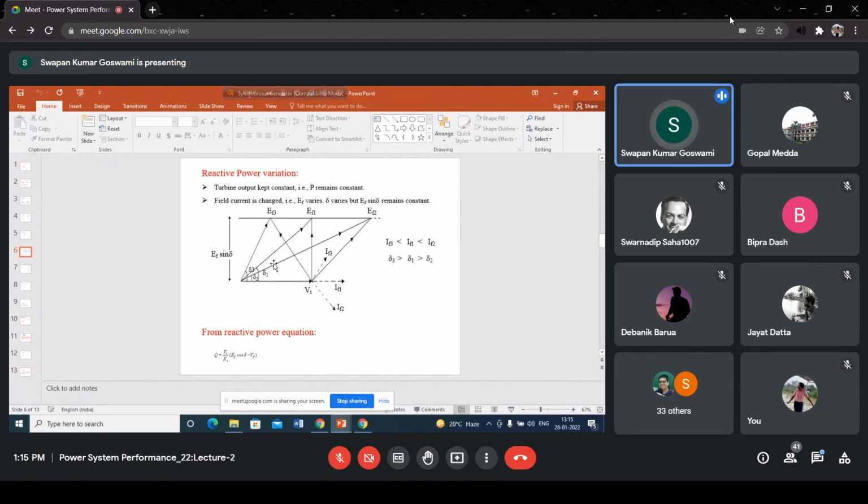So for this phasor diagram, say EF1, the terminal voltage, the infinite bus voltage VT, is always fixed. Then VT plus jIA1 Xs, we are getting EF1. For this one, it is VT, then jIA2 Xs, that means 90 degrees with this is the direction of IA2, and we are getting EF2. This is EF3, so VT plus jIA3 Xs. So the direction of IA3 is this one.